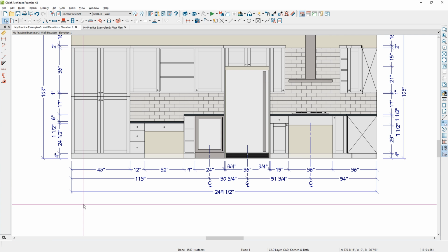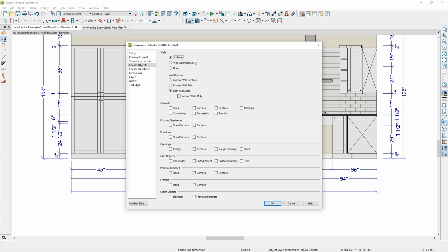get it set up. Again, I like to use the automatic dimensions. I use it all the time. Once you get used to dimensioning and you can build your own annotation set with what's turned on and off in your locate, it can be very powerful to do your dimensioning quickly.